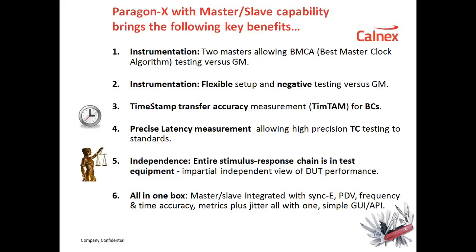So the Paragon-X has everything in one box, master-slave integrated with SyncE, packet impairments and packet metric recovered clock measurements, plus SyncE physical layer jitter measurements, all under the control of one simple GUI or API.